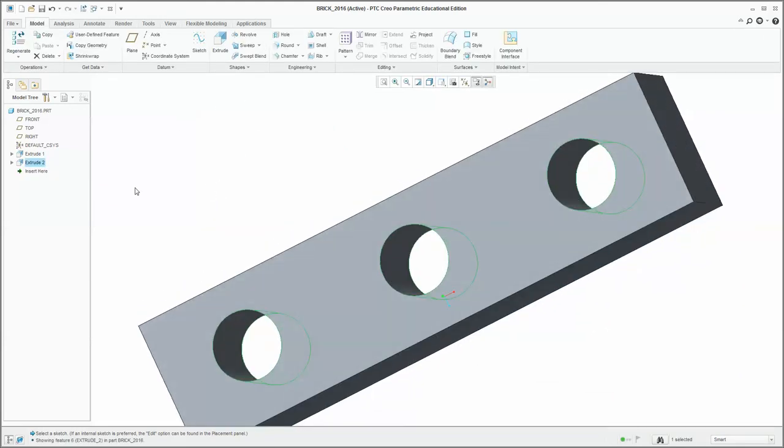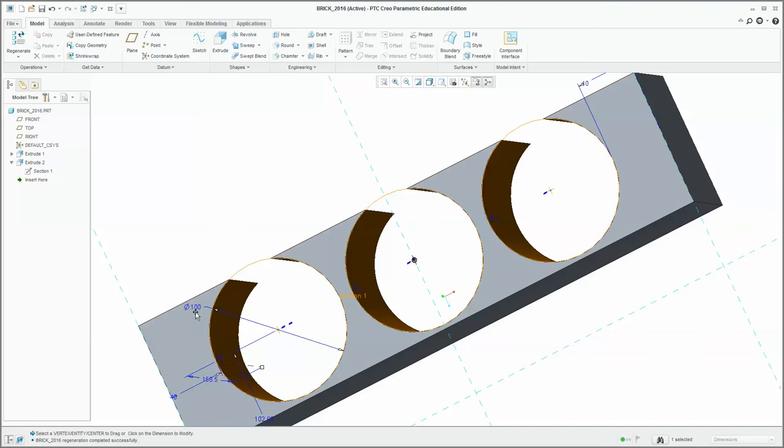But you're going to make mistakes. So how do you fix it? Let me show you. On the left over here, we've got a number of extrudes. The first, simplest option: delete the extrusion, and that will get rid of any changes that have happened on the screen. But let's say I want to edit it. I can click here, I can right click, and here I can get some of my measurement features back. So here I can see I've got my little radius here, but let's say, oh, I really want that to be 100. Bang, I can change it very, very quickly within the screen itself.